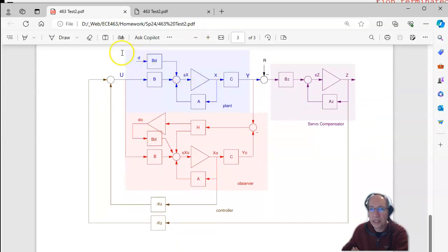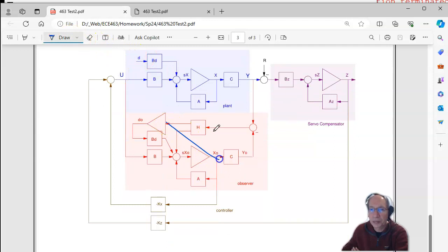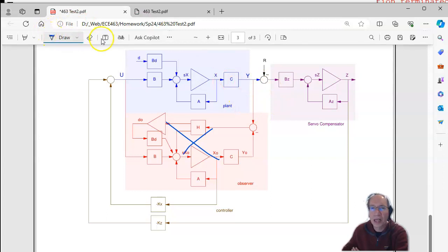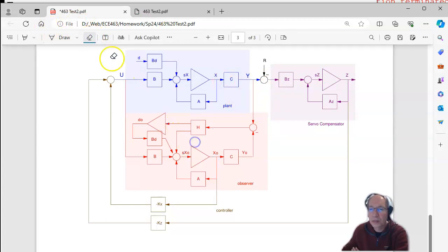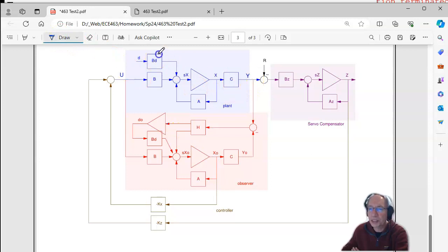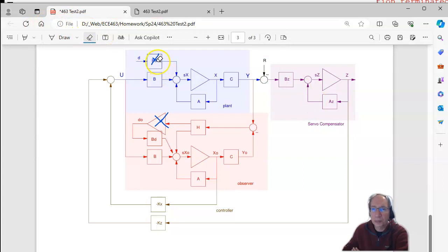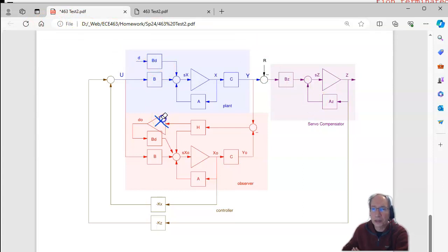At the C level, I don't need the observer, and I just use full state feedback, get this to work. At the B level, I need the observer because they only measure position and angle. There is no disturbance, so this you don't need at the B level. Design a full order observer to track the plant and track a sinusoidal set point. At the A level, it's now a disturbance, meaning the observer has to estimate that constant disturbance, track a sinusoidal set point, while only measuring position and angle.